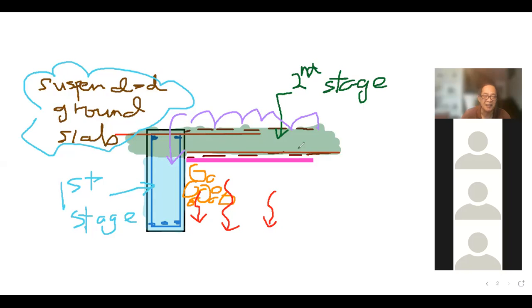So in this stage now, in this case, what we have is a suspended ground slab, in the sense that it will behave as a typical slab at level number 1, level number 2, at the upper floors, macam a typical slab yang biasa. Loadings on the ground slab will then be transferred kepada ground beam because now the ground beam is supporting the ground slab.